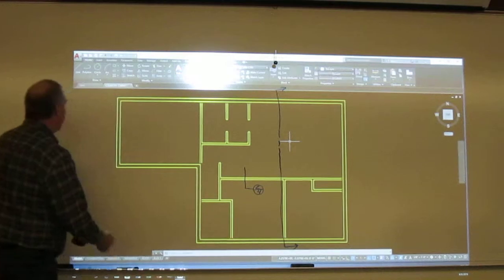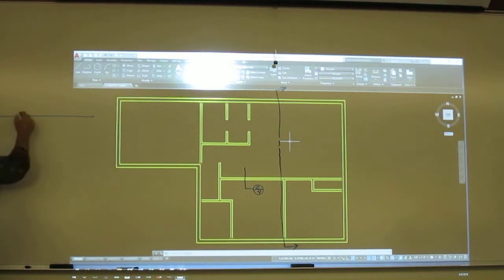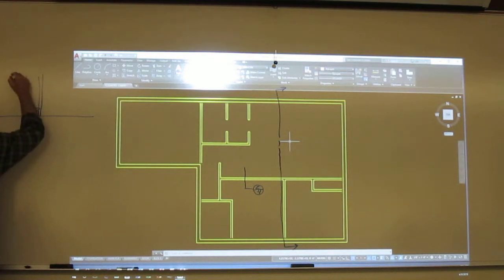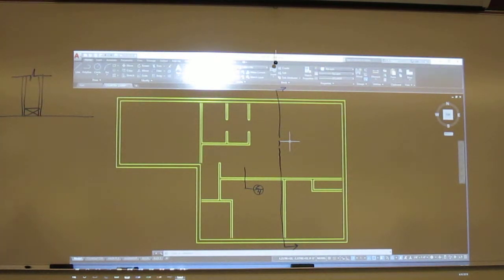Now when you go ahead and draw that, what you're really going to see is the concrete floor. We have a wall that then comes up from there. And it's a 2x4 wall, so it will have drywall on both sides. We don't need to show much of it. Just some of it like this to know that it's there and we can call it out. Now what's going to go on with the footing here?